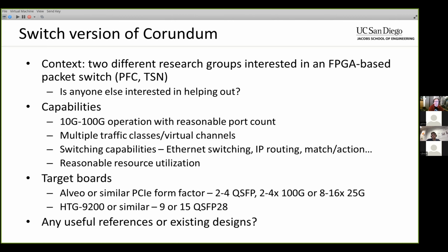Yeah, I think it is implemented in PTP for Linux probably, also. Right, yeah. I guess PTP4L could probably use either. It's just a question of whether the hardware supports it. But to do the one step that you need for transparent clocking, the MAC modules on transmit have to be able to modify the packet as it is being sent. And that, let's just say, adds a lot of complexity.